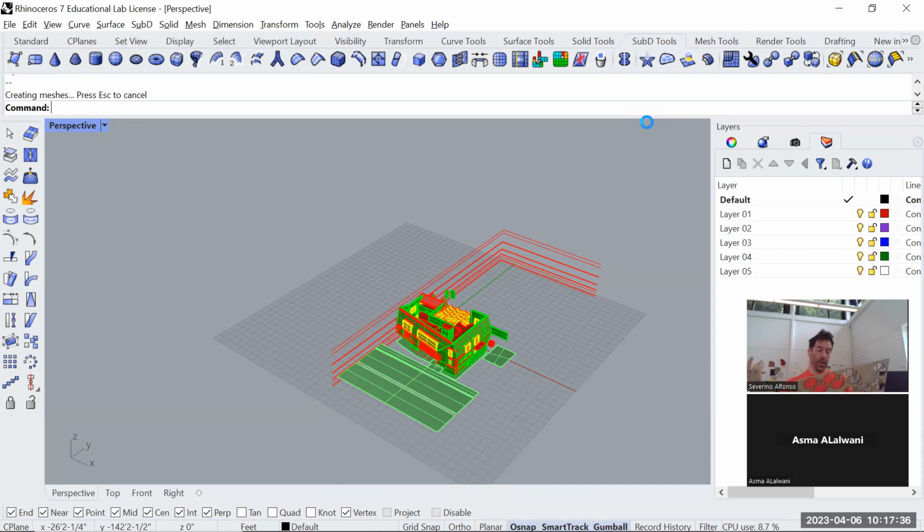And what the machine does again is very simple. It just goes along the line that you have drawn. So if it's an AutoCAD line, it goes there. But imagine you have 3 lines by mistake in the same place. It will go 3 times. So you need to have single lines. Yeah, so AutoCAD has an option called overkill, I think it's called the command. It kills the double lines and triples and stuff.